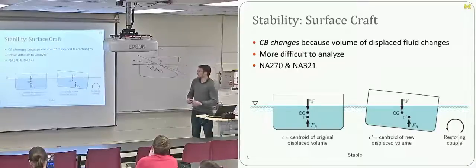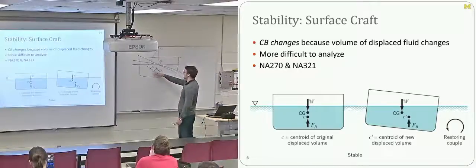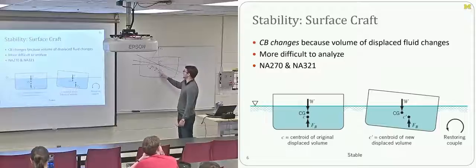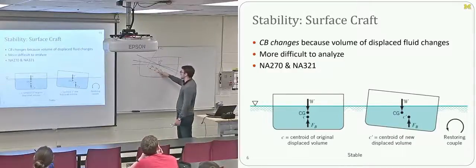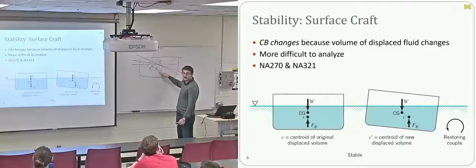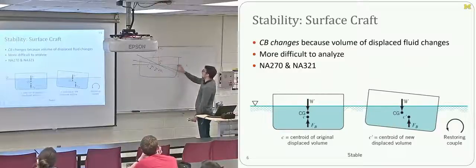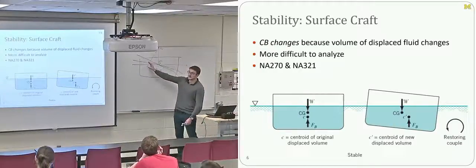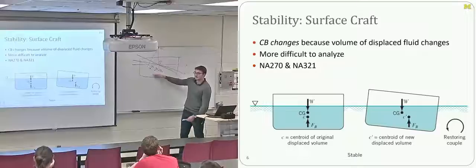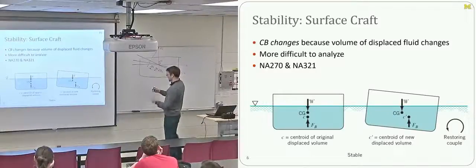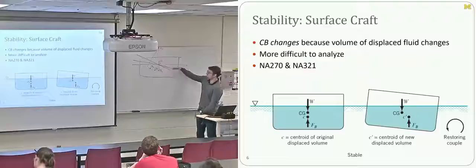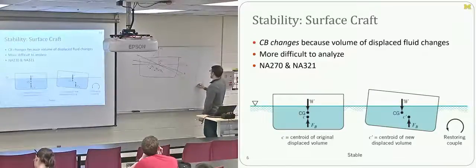I guess I'll say one more thing about this. The idea is that because the metacenter depends on how far your center of buoyancy swings with small changes in the heel angle, it's highly dependent on how much volume you lose and gain on each side relative to how much volume stays immersed. Which is why if you have a body that's shaped like this, something that's relatively shallow and wide, compared to a really deep spar, for example,